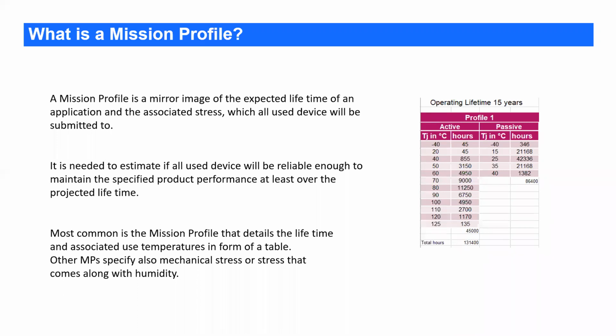There are other mission profiles that relate to other stresses in the field, and I think the next one that is widely used is temp cycling to mimic thermomechanical stress. And you express this here by delta temperatures and also how many temperature variations this device will see in the field.